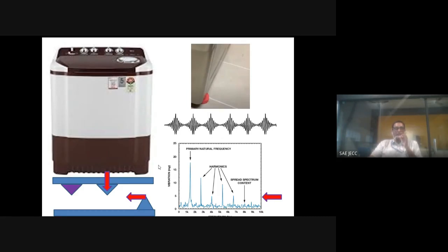So what you are actually doing, you are reducing the spindle speed of this particular device, and suppose it is coming from say 2880 and it is gradually coming to 0. So in that case, it is crossing certain natural frequency modes of this system. Once your operating frequency matches with the natural frequency, resonance happens. And there will be multiple modes, and you can see that whenever it crosses different modes, this type of jerks are observed. Now, the frequency domain representation of different harmonics is shown here.